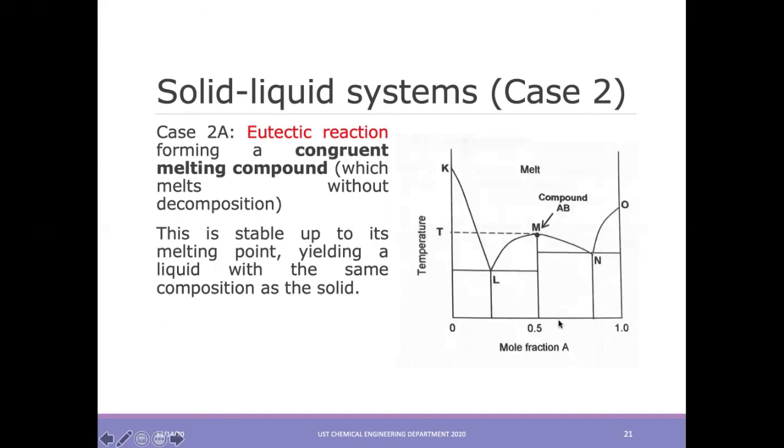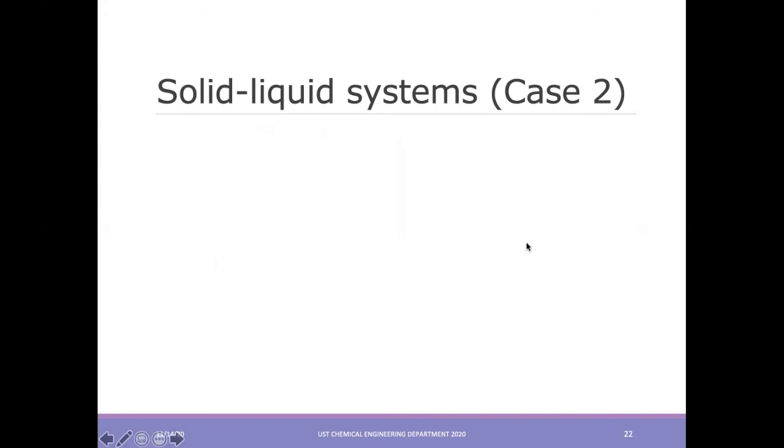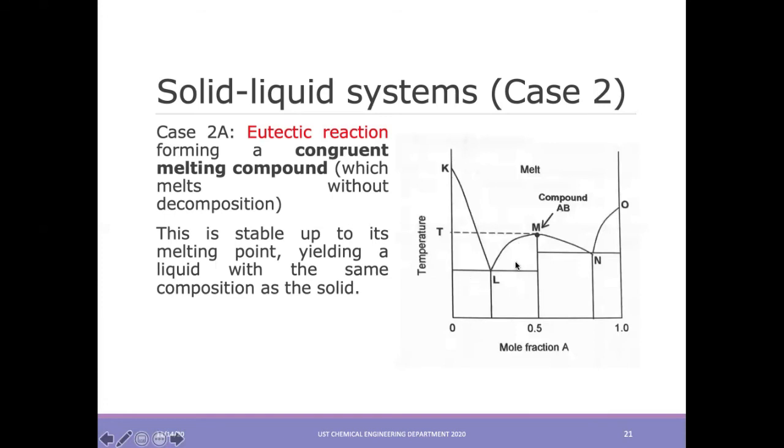At this point, below the curves LM and MN, it consists of saturated solution of AB with solid AB. The composition of a two-phase system could also be deduced through the use of a tie line drawn at a given temperature. The lever rule enables the calculation of the relative amounts in each phase.